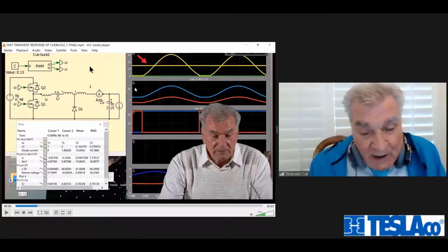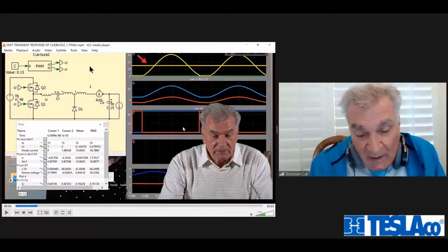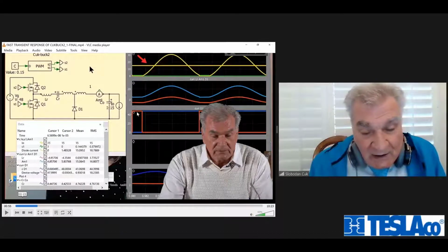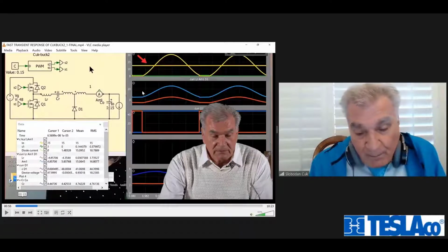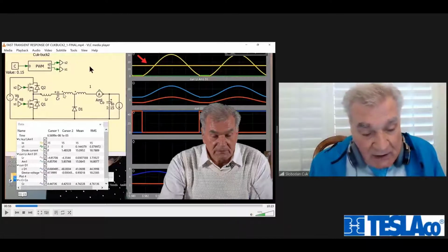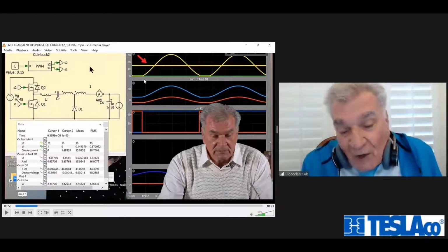It is sine wave current. So you are driving this transformer from here to here with the square wave voltage that you see here, but the current in the primary is a sine wave. And what is the current in the secondary? The current in the secondary is set by whatever the turns ratio is to step down the voltage. This is now a step up of current. If it is 2 to 1 step down in the voltage, it is 1 to 2 step up, so this current is twice larger. And what is then the sum of this current and this current in the secondary, who are split? The two together result in a diode current which is at zero level.